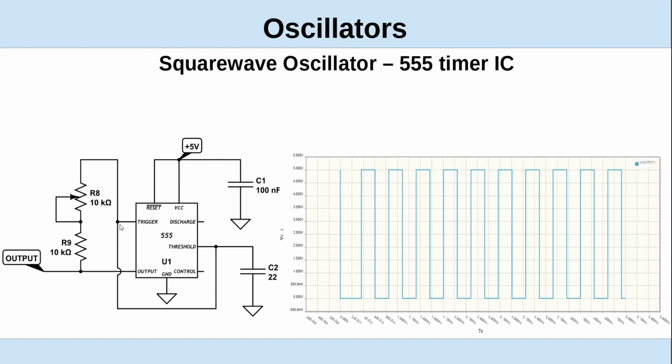So however long it takes to charge this capacitor affects the period of the waveform, and it's set internally with the trigger value. As it starts charging up, when it gets up to the trigger point, it discharges it and then starts all over again if you configure it as an astable multivibrator.